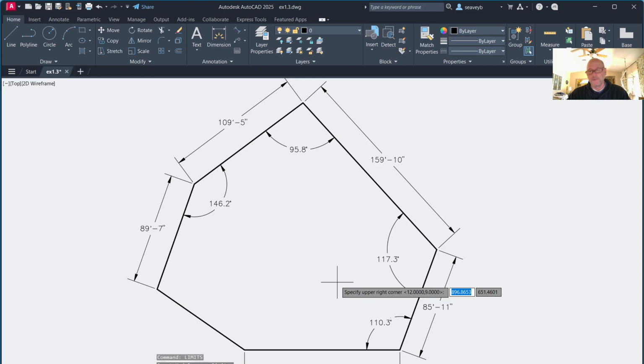We'll be able to zoom in and out of that. So 200 inches ends up being what, 1200, 2400, 200 feet is 2400 inches, right? So I'll type in 2400, comma, 2400. So that puts 2400 inches, 200 feet to the right and up as the other opposite corner of the rectangle of the limits. So even though the screen isn't rectangular, it should be pretty good.